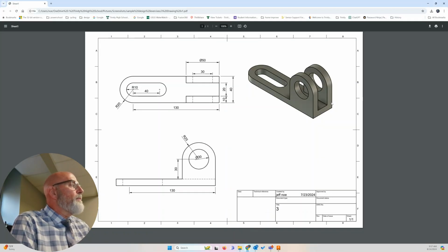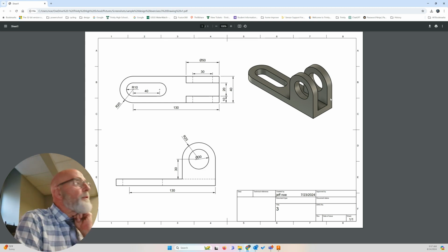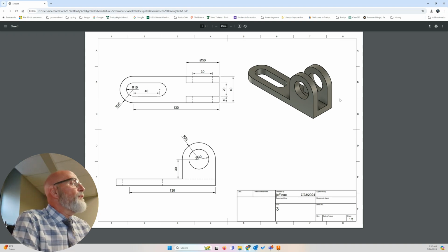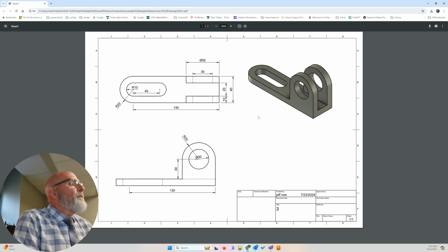What we created was a solid across here, and I find it easier to take a subtractive approach. So what I need to do is cut away a rectangular shape here in the middle. And that rectangle, so I'm going to create my sketch on this back face. I'm going to draw a rectangle.